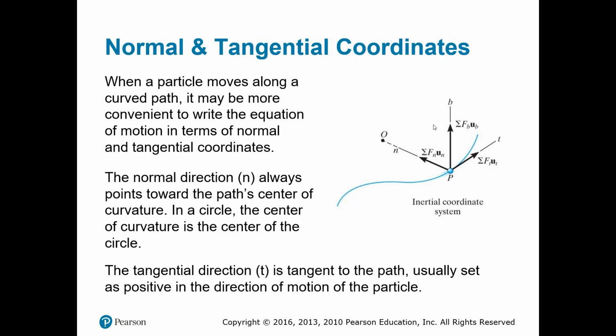And I want to stop myself right now because what you need to realize is that this is just another x and y, but we're just using another coordinate system very similar to what we had before. What we need to consider here is just the direction for each one of them. The tangent components are always tangent to the path, and the normal components are always pointing to the center of this curvilinear path. This is important because we have acceleration involved, two components for acceleration, and then we have the change in the position, the change in the velocity when we're studying all this movement.